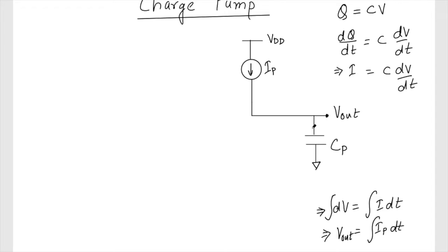This we generally use even in op-amps. When we want to get an integrator, we use a similar kind of expression. We generate a constant current source and pump it into the capacitor. So the voltage that is developed across this capacitor CP is the integration; as we pump this current slowly, because my I is constant, the voltage is going to increase slowly in an integral way, something like this.